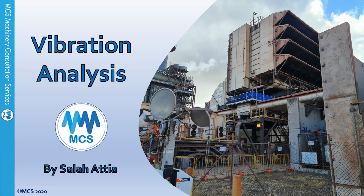If you look at the linear range of your accelerometer, you will see that above a certain frequency, like 2 or 3,000 hertz, the vibration will be magnified automatically because of the accelerometer's response itself. If you have any small amount of vibration at very high frequency, it will be excited in this range. That's why it appears with higher amplitude at higher frequency, because it is an event with very small amplitude and very high frequency.